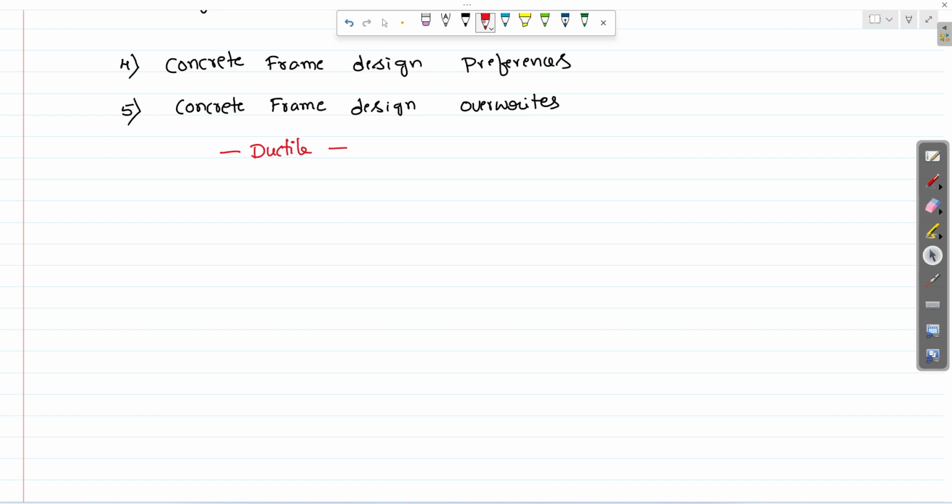All beams are designed as per IS 13920. Only if you have applied earthquake loads should you select this option.